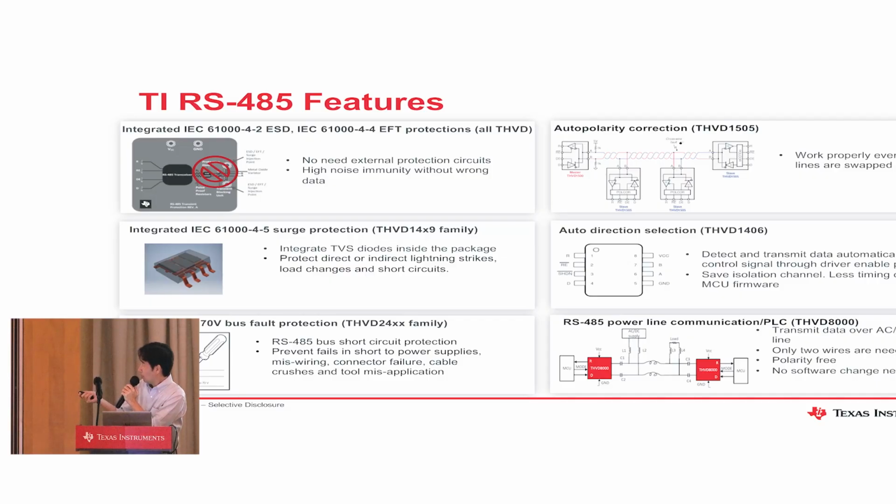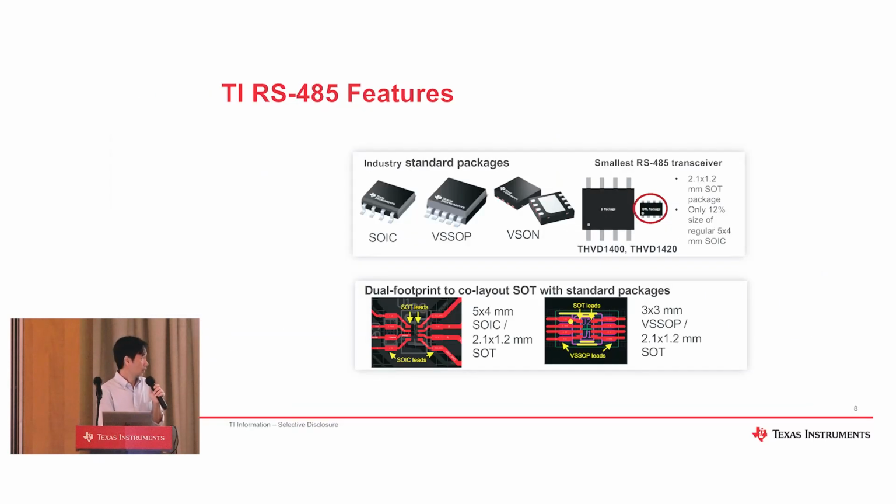And the other one is the auto direction feature. For this type of device, you don't need to use an MCU or any other host in the system to decide which direction to transmit or receive the data. The device can automatically detect the direction and transmit the data.